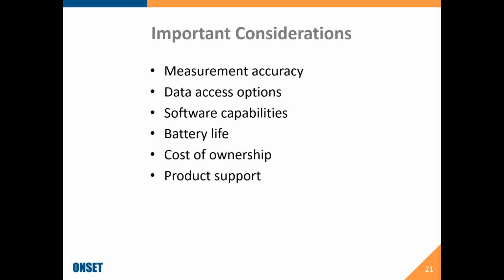Considerations in choosing that: I'd probably also ask, what kind of accuracy do you need? Typically, our data loggers are very accurate. They're 2/10 of a degree C, which is about half a degree Fahrenheit. We also have some lower cost data loggers, as low as $54 for a simple underwater temperature data logger. That one is plus or minus 1 degree Fahrenheit in accuracy. But people love them because they can put out a lot of data loggers to profile a large area. It's an important piece of getting as much data as possible.